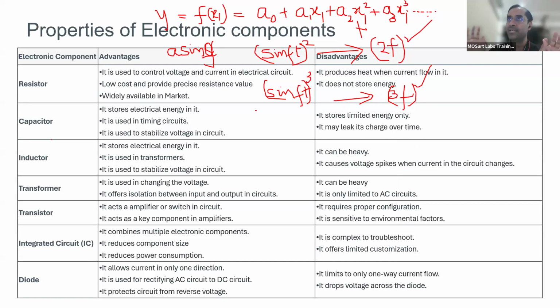All these harmonics come. So the problem with the non-linearity of the circuits is that if you give one frequency, a core fundamental frequency, one tone, it will generate 100 different tones of all the frequencies, all the harmonics. That is nothing but your distortion. Let's say for a nice audio amplifier, you give a 1 kilohertz sine wave, and as you keep increasing the amplitude, at some point you will hear a screeching noise, and that is because the sine wave got distorted. It got clamped and it generated many frequencies.